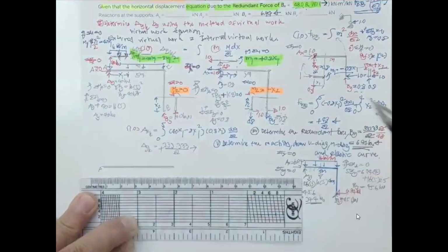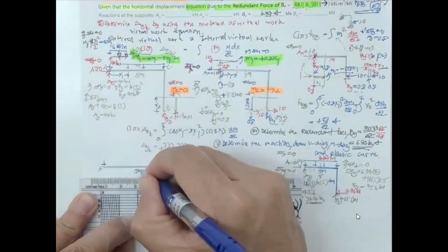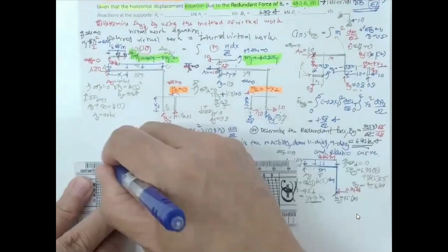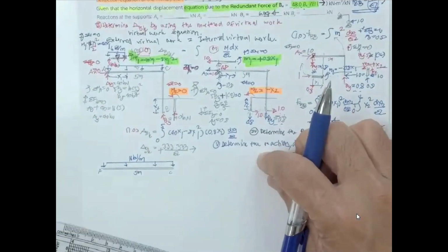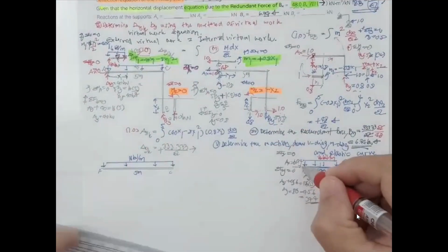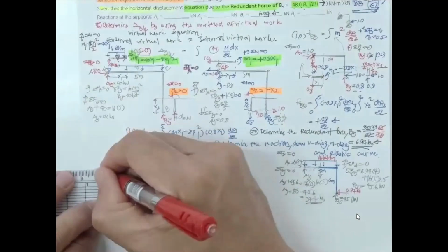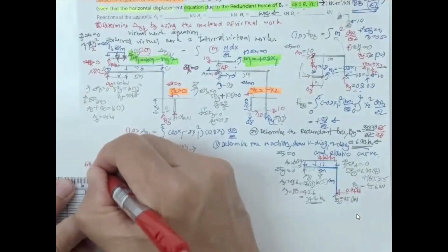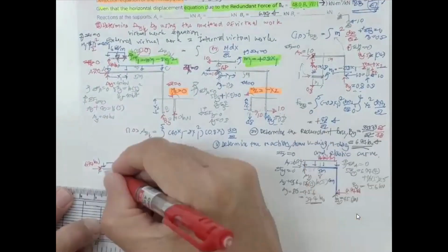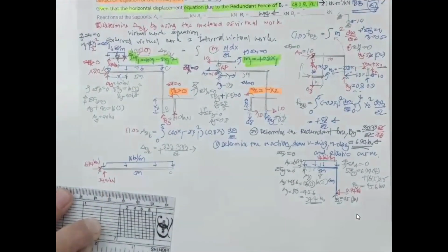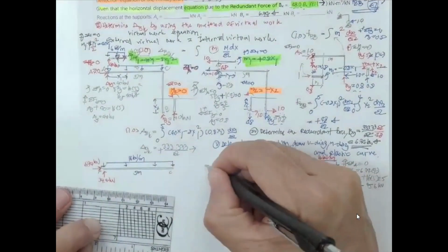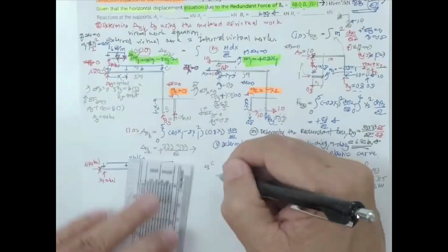Okay, that's gonna be the beam A, and that's gonna be C. And then we have this portion to be 5 meter subjected to uniformly distributed load 16 kilonewton per meter, and this portion subjected to 6.94 kilonewton, and A sub y over here, that's gonna be 34.4 kilonewton.